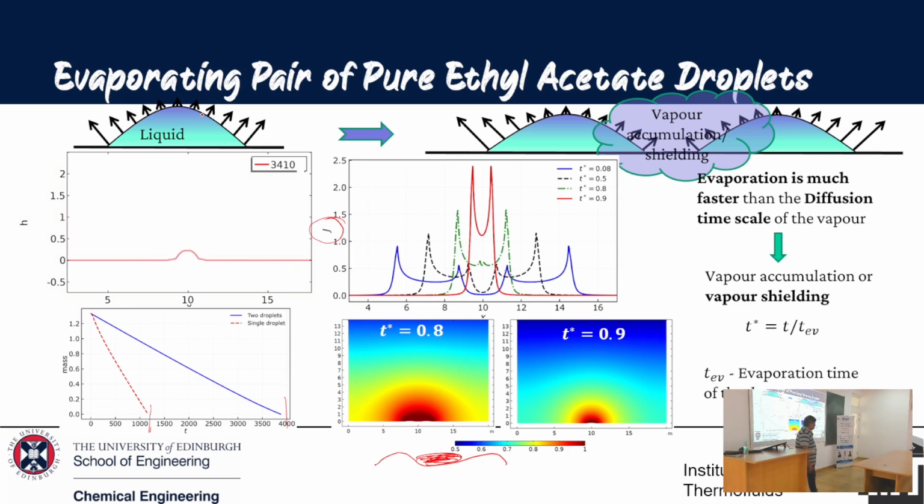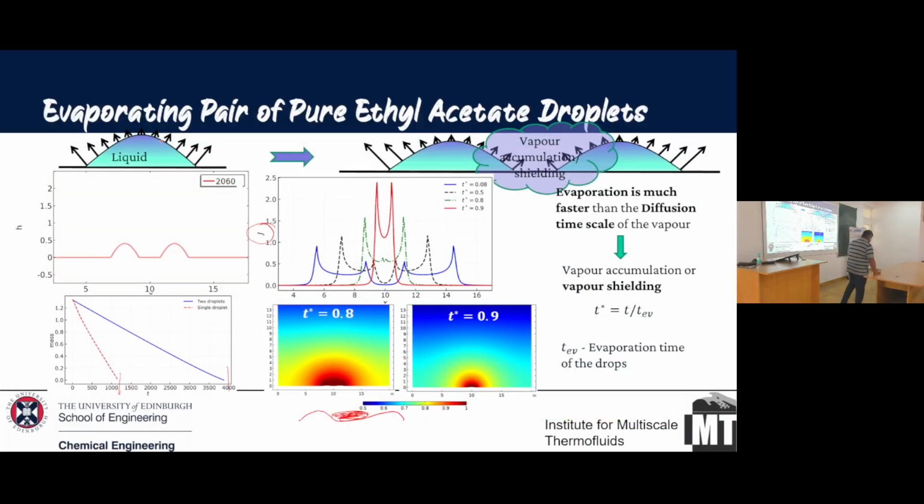And is this spreading and evaporation simultaneously taking place? So is it controlled by inertia of the droplet or heat transfer? Yeah, good question. At least on the modeling side, because it's a lubrication theory, we've killed most of the inertial terms. But when we do numerics, we find that inertia does play a role, especially in the region of contact angle of 40 degrees to 60 degrees, where inertia plays a huge role.